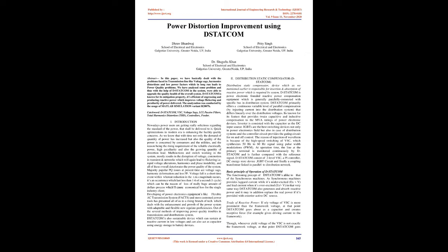The development of power electronics equipment like flexible AC transmission systems, FACTS, and more custom power tools has introduced all of us to a rising branch of technology, which deals with the enhancement and growth of the power system with adaptable and flexible new control capabilities. Out of the several methods of improving power quality problems in transmission and distribution systems, D-STATCOM is also a sustainable device which can sustain reactive current at low voltages and can also act as a capacitor using energy storage in battery devices.